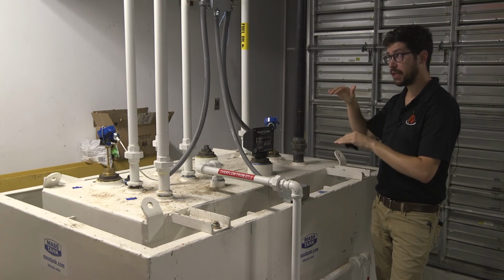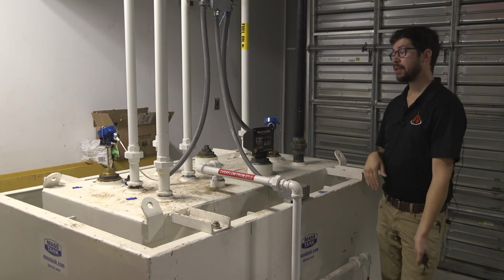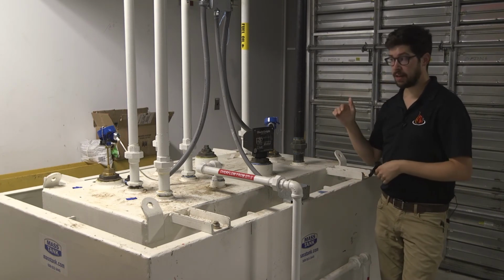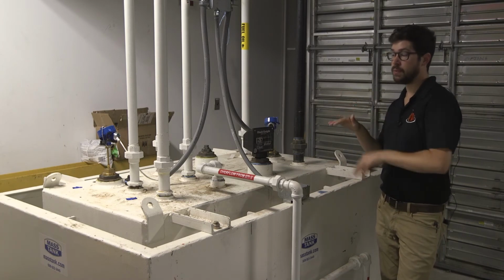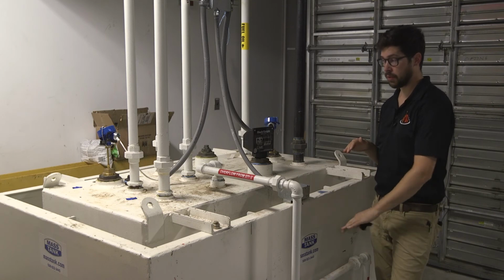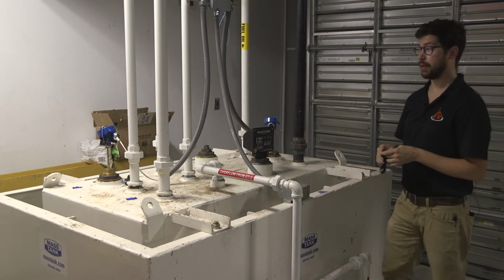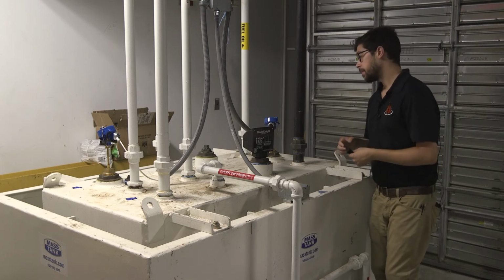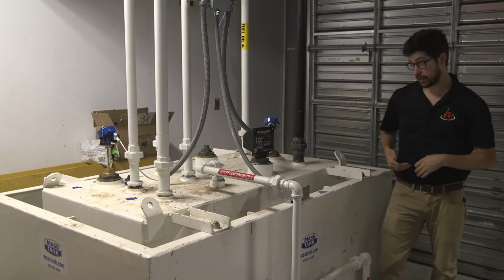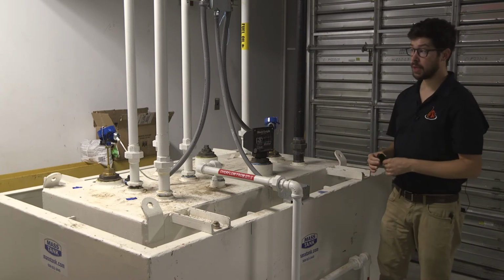Then I believe it is 50% for the pump on. So when the tank gets down to 50%, it turns the pump on, pumps it up to 85%, and it should always live within that level. If it continues to drop to 40%, we cause the alarm, and bells and whistles start flying. And then typically, if it goes down that far, you're saying, hey, there's probably something wrong with the pumps.